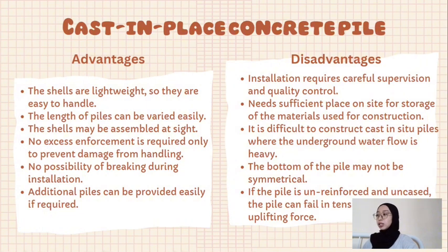cast-in-place concrete piles. This type of pile footing is constructed by boring soil up to the desired depth, then depositing freshly mixed concrete in that place and letting it cure there. Cast in situ concrete pile foundation is constructed either by driving a metallic shell into the ground and filling it with concrete and leaving the shell with the concrete, or the shell is pulled out while the concrete is poured. Usually, round piles are used in cast in situ piling.